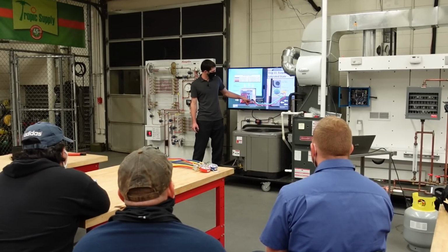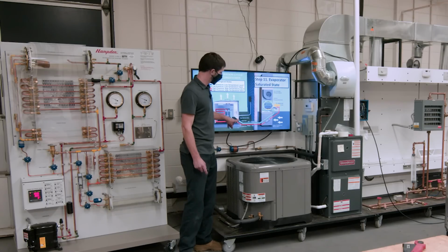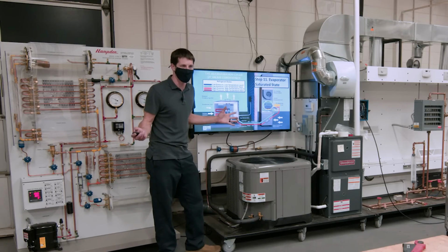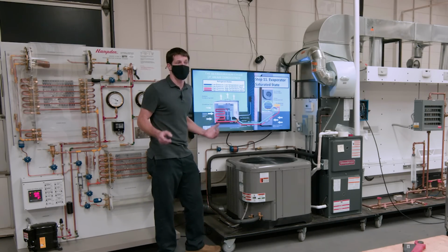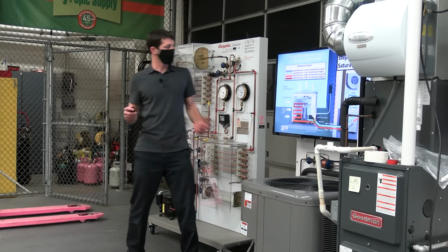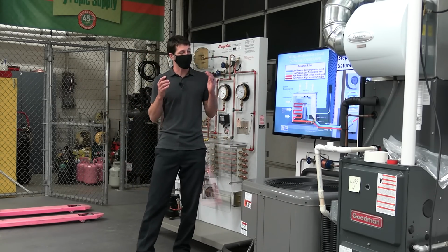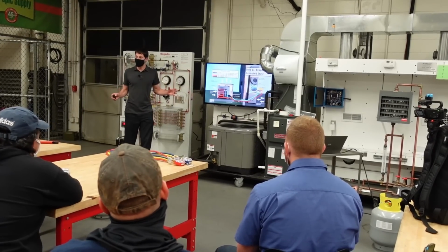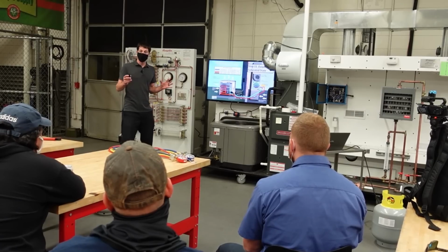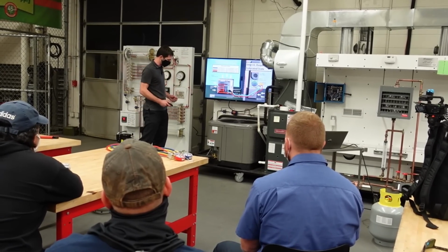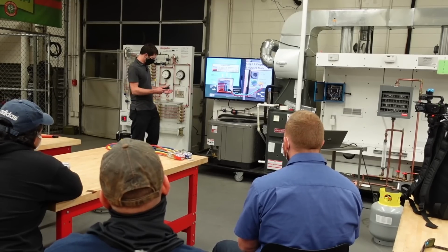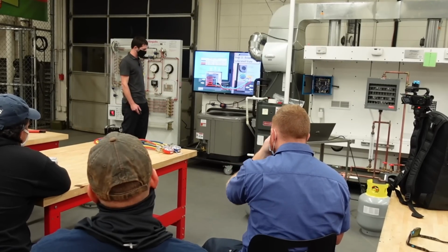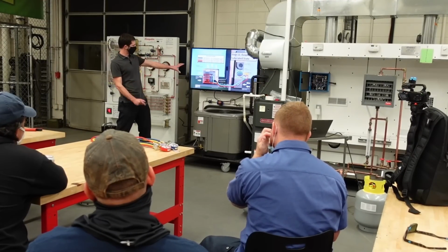And remember, you're checking your pressure out here. So when somebody asks me what pressure it should be, I already know what's going on in their mind, meaning that we got a lot of work to do. You've got to stop talking about pressure and think about saturated temperatures and line temperatures. And then, once again, the crazy thing about this is, this is not a joke at all. You will have your gauge set on. You will have your 2 temp meters on. You will be reading your superheat, your subcooling, and you see your low side sat and your high side saturated temperature. You can picture all of this happening.